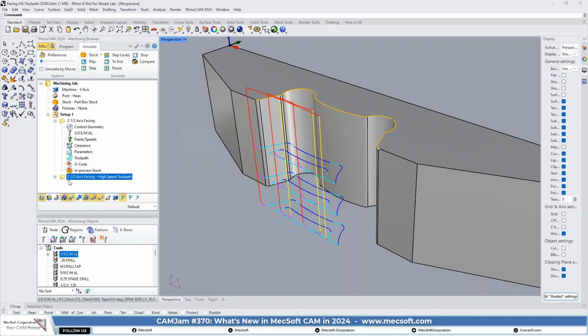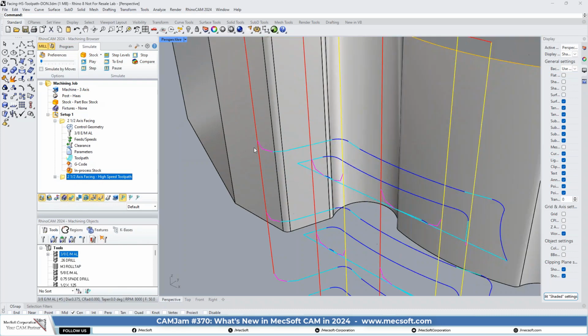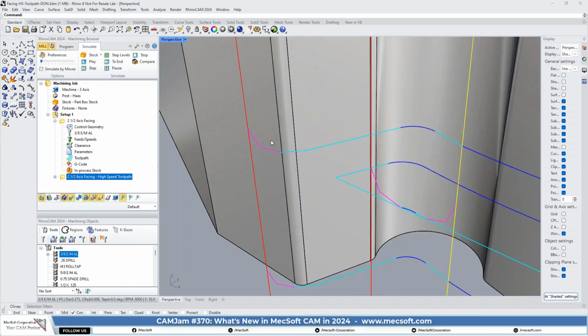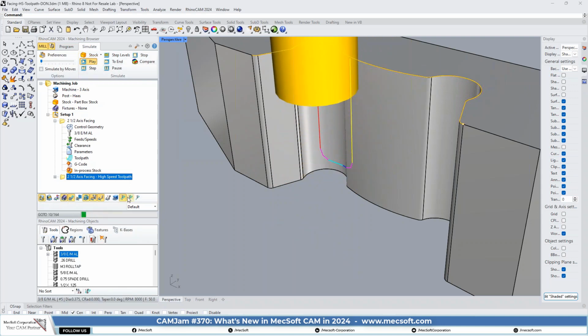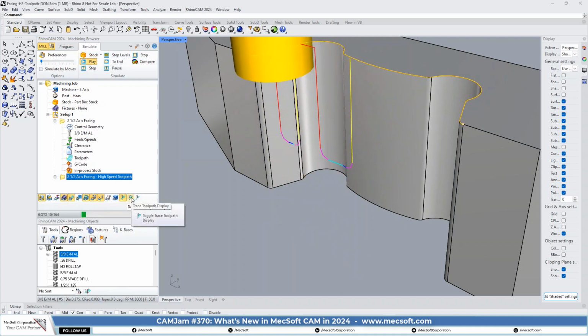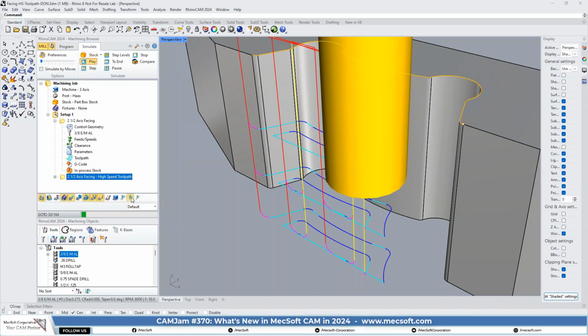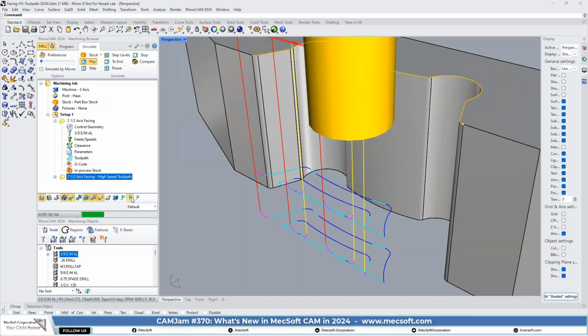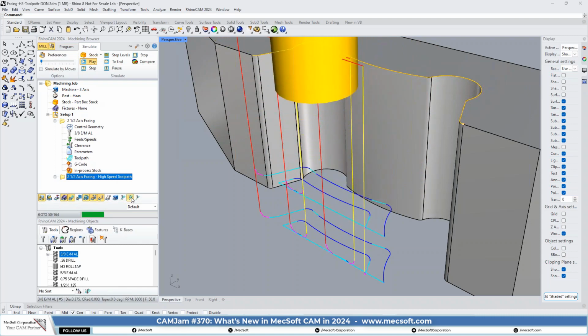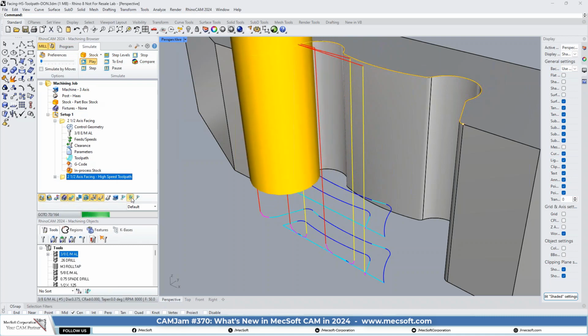You'll see that with the high-speed cut patterning in the facing, it adds these arc motions going from one level or from one area on the toolpath to the next. Let's play that. It also adds arcs in the toolpath itself, so you can see the arc motions. There are some sharp corners you can still see, and we are working on that when we release this product. Even those sharp corners will be adding arcs at that point also.